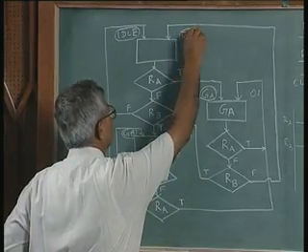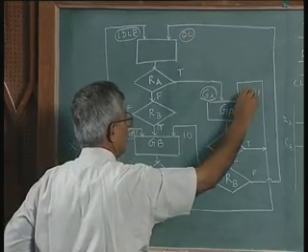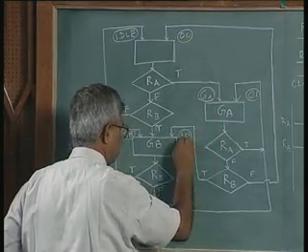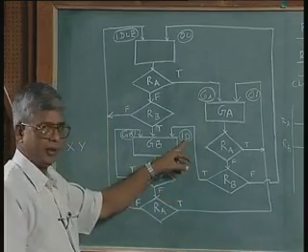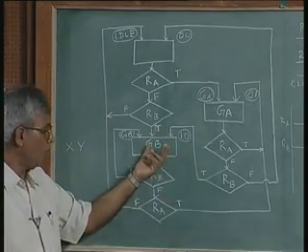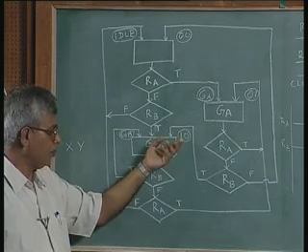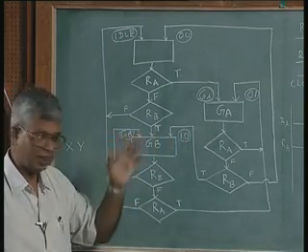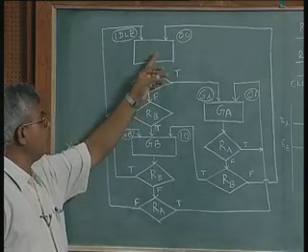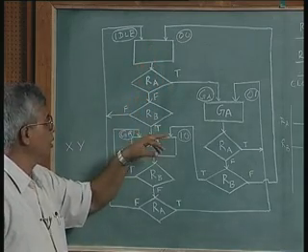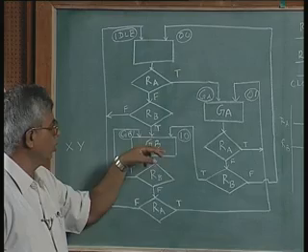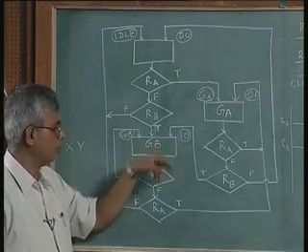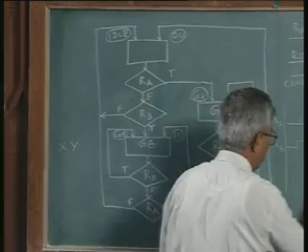It is always again a convention to put a circle around the states. The state assignment, as it is called, is marked outside the box on the right hand top and enclosed in a small circle. This is a convention again. So there are 3 states: idle state whose assignment is 0 0, GA state whose assignment is 0 1, GB state whose assignment is 1 0. So, state assignment.